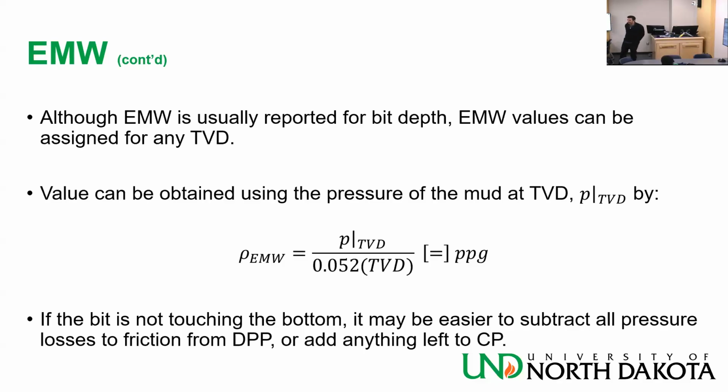So before you start drilling, just circulate at a certain rate that you expect to be drilling. If I'm going to be drilling at 140 SPM, I will circulate at 140 SPM and read the pressure on the drill pipe for that, and I will record it. That is a good indication of the frictional losses that you encounter throughout. Because whatever depth I gain, I will lose coming up. So hydrostatic wouldn't matter.